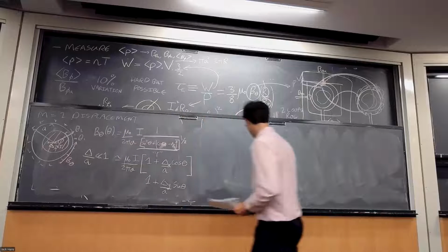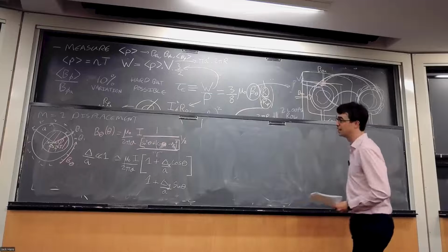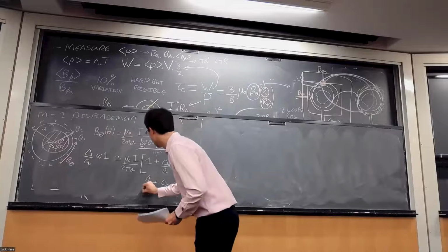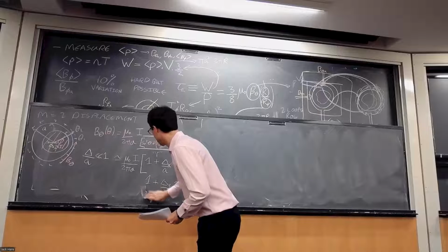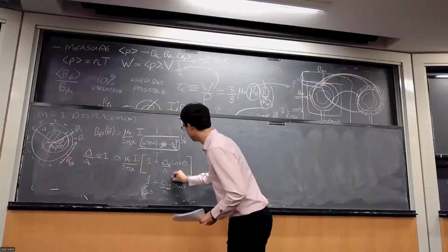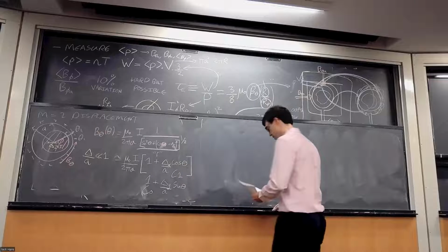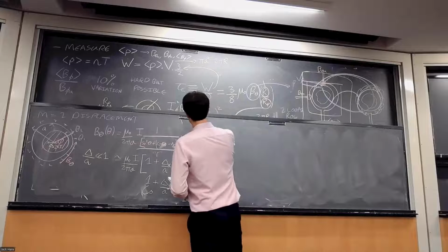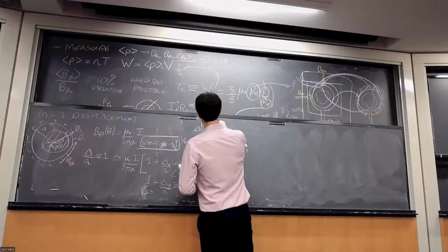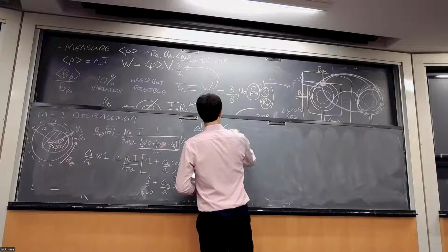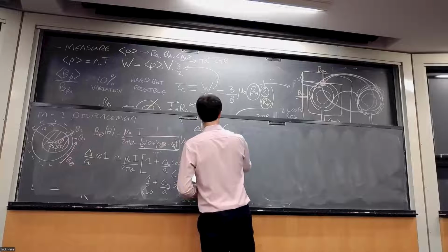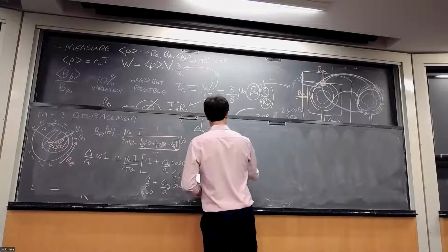And if you remember the Fourier decomposition that we said we were going to do at the start, for this magnetic field pattern there are only 2 terms. This is the C0 coefficient, and these 2 are the C1 coefficients. And so we can directly measure the displacement in x as 2a C1 over C0, or the displacement in y as 2a S1 over C0.